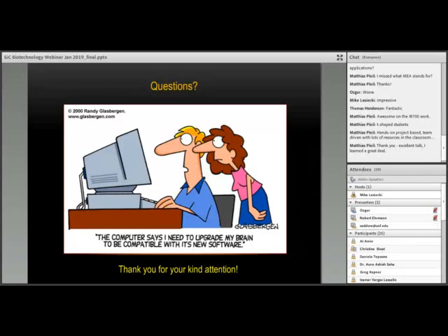Let's follow up on another of his questions. Any litho challenges? You're not really talking about small features here, are you? For the neural interfaces, they're more or less micro scale, but for the nanotexturing, yeah, we're talking about 50 nanometer diameter little cylinders of silicon carbide. We're trying to etch them very deep. For the DNA sensors, yeah, those are very, very narrow nanowires. The nanoparticles for the cancer, yeah, they're 8 to 10 nanometers, right? So we're talking about nanoscale. Also the nanowires are typically 50 to 60 microns in diameter. But there's always one dimension rather big, right? I hope that answers the question, Mike.